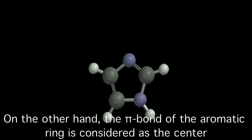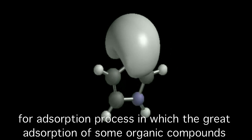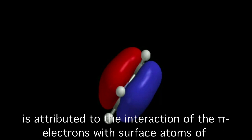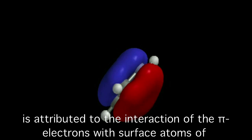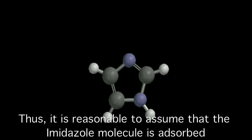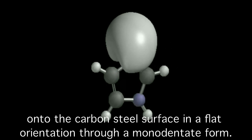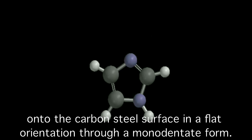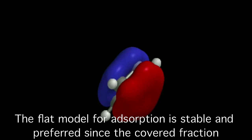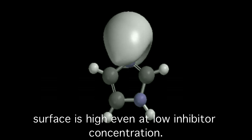On the other hand, the pi bond of the aromatic ring is considered as the center for the adsorption process, in which the great adsorption of some organic compounds is attributed to the interaction of the pi electrons with surface atoms of the adsorbent. Thus, it is reasonable to assume that the imidazole molecule is adsorbed onto the carbon steel surface in a flat orientation through a monodentate form. The flat model for adsorption is stable and preferred since the covered surface fraction is high even at low inhibitor concentration.